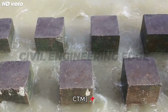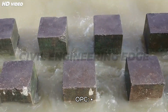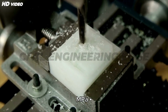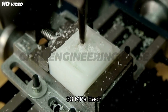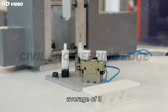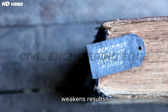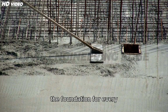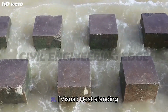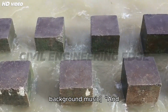Minimum strength for OPC: 3 days, greater than or equal to 16 megapascals; 7 days, greater than or equal to 22 MPa; 28 days, greater than or equal to 33 megapascals. Each result must be the average of 3 cubes. Tip: never use old or lumpy cement, it weakens results. Compressive strength forms the foundation for every RCC structure, from slabs to skyscrapers. Visual: host standing in the lab with test equipment and cement cubes around, upbeat background music.